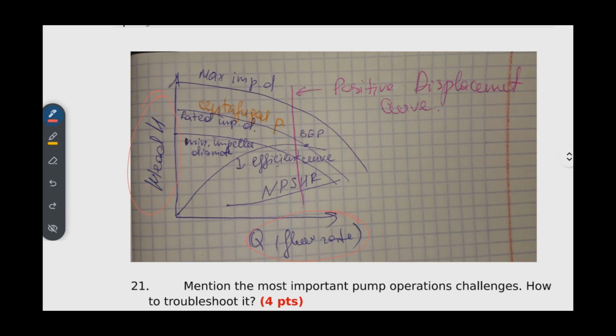On the y-axis, as you can see, we have this kind of line, which is going like this. For the centrifugal pumps, the head and the flow rate are dependent not proportionally. I mean, for example, the head will be like 1 over Q flow rate. As you're increasing your head, this side will be decreasing. It means that at your maximum flow rate, you don't have any head. At your maximum head, you don't have any flow rate. This is the dependency for centrifugal pumps.